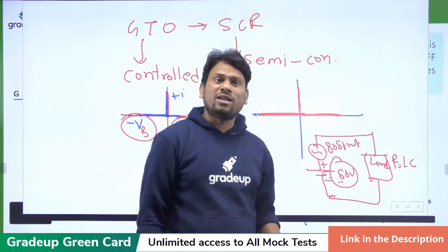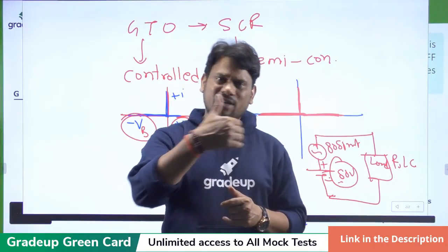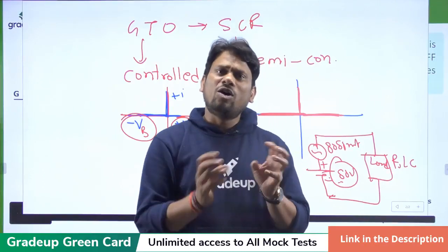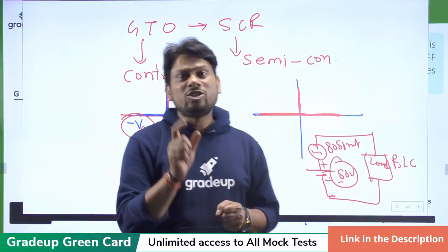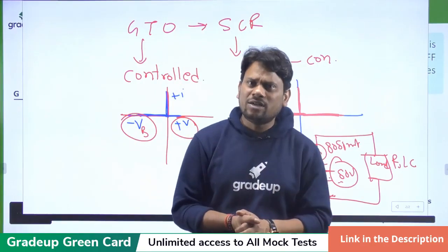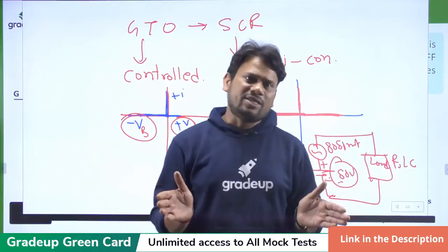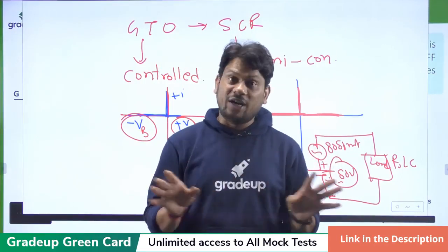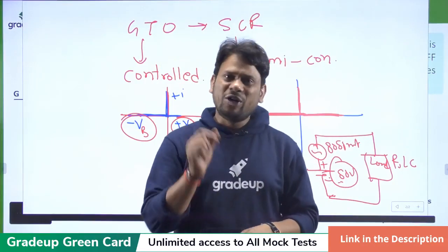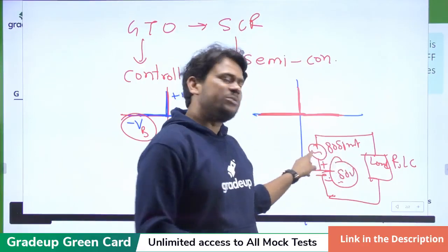That type of signal or that type of circuit, always we have to solve by superposition theorem, because superposition is very, very important when our circuit is going to operate by different frequencies simultaneously. We don't have any second choice to handle that type of circuit.